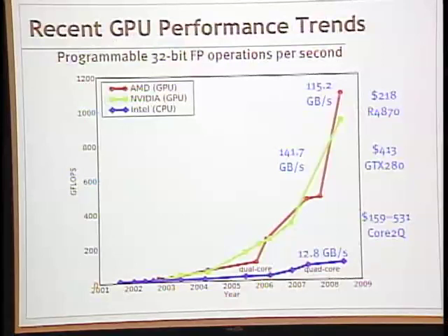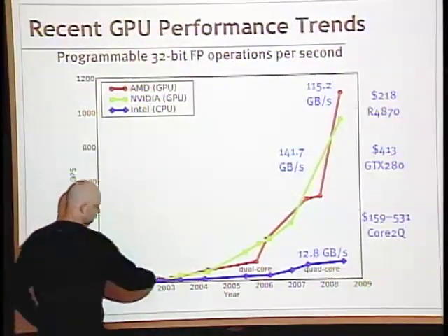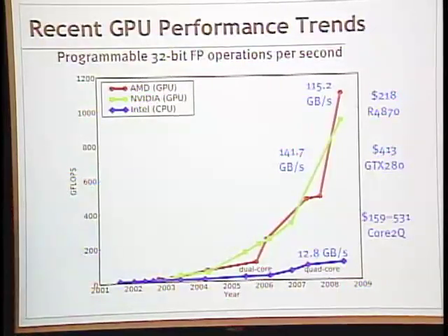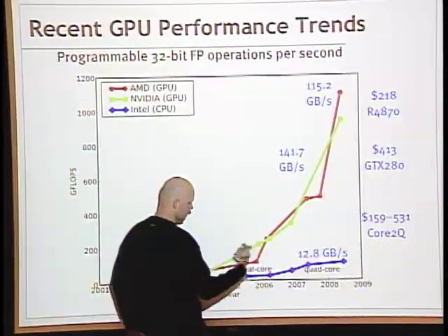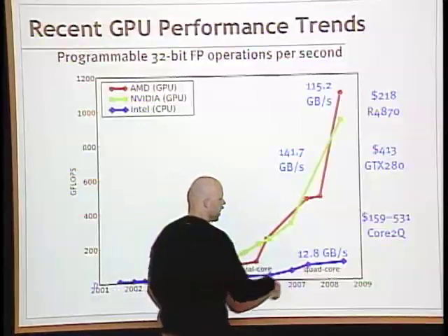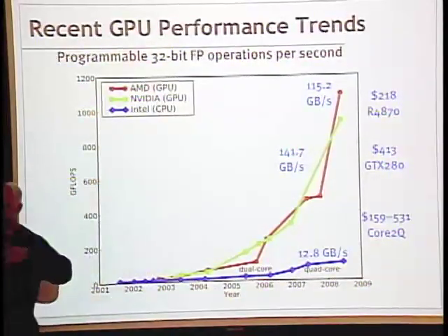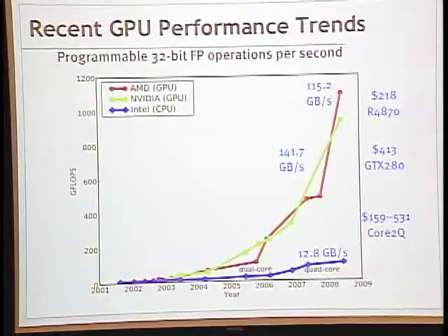Okay, so the other figure of merit I wanted to go over, and I'll show this graph more than once in class because it comes up a lot, is just how much performance can you get out of a GPU? What's the raw amount of performance? What we're showing here in blue is the maximum performance you can get out of an Intel microprocessor. You'll see a couple of jumps in this graph. There's a jump here where we went to dual core machines. There's a jump where we went to quad core machines. If all you're doing is floating point operations over and over and over again, how many can you fit? With a quad core machine, you're getting roughly 100 billion floating point operations per second, which is pretty good, and better than it was a few years ago.